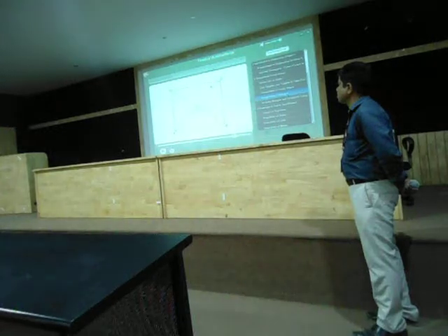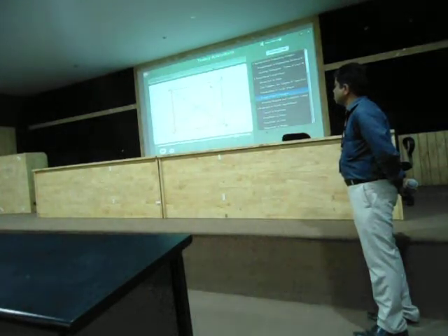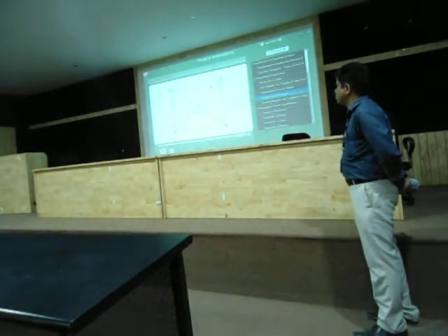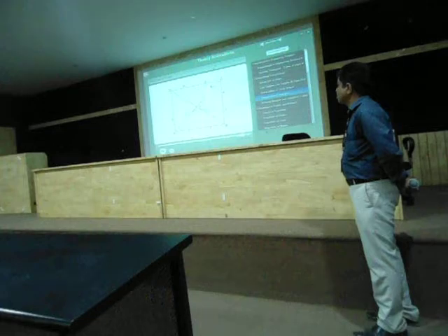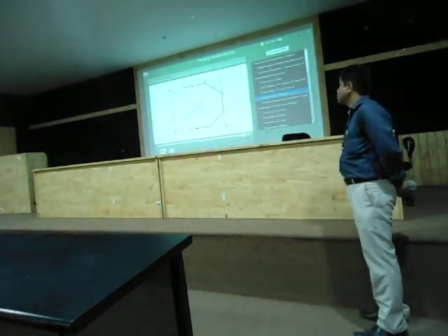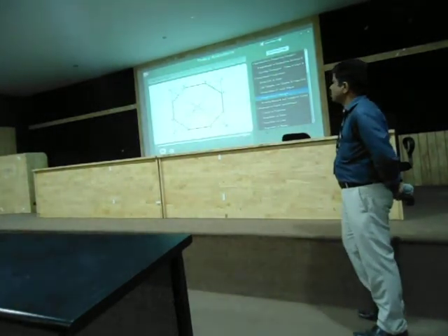Then with A as center and AO as radius, draw an arc cutting edges AB and AD at points 2 and 7 respectively. Similarly, with centers as B, C and D and radius as AO, draw arcs to obtain the remaining points. At last, we join the points 2, 3, 4, 5, 6, 7 and 8, 1, thus completing the octagon.